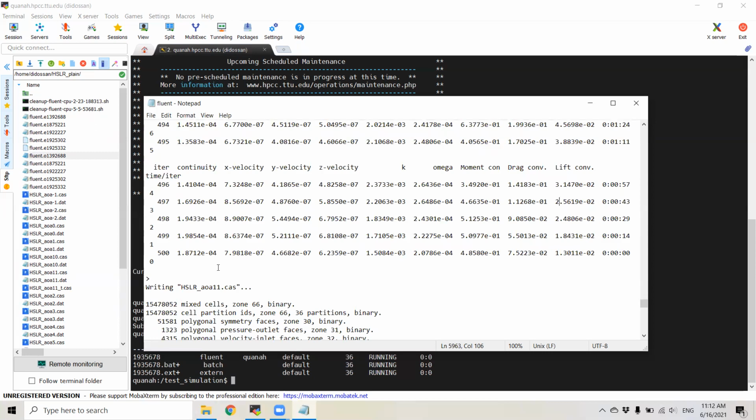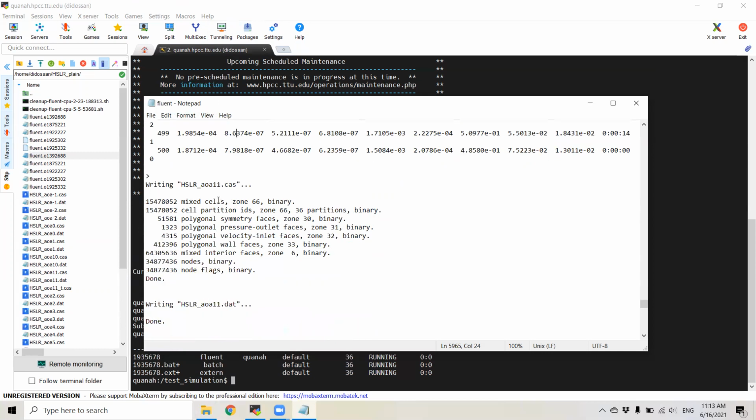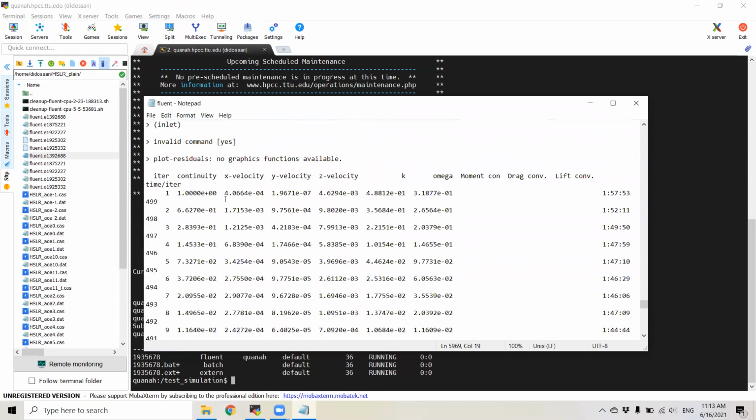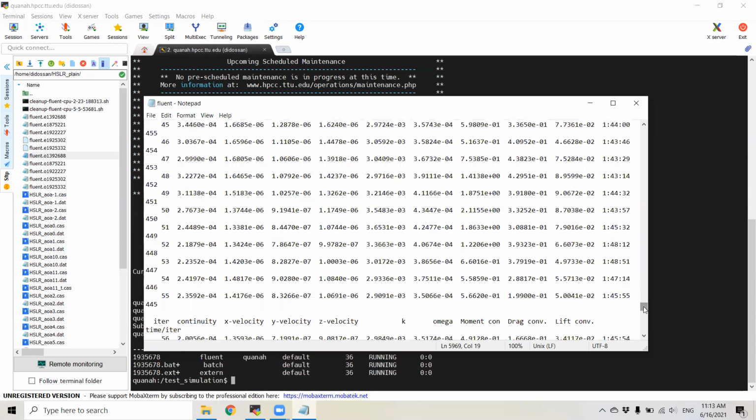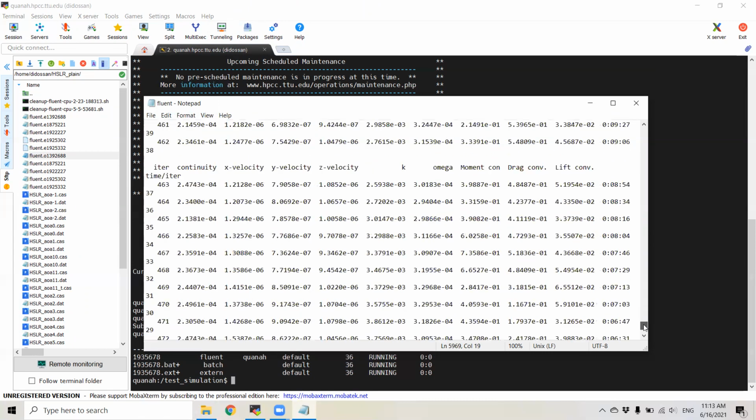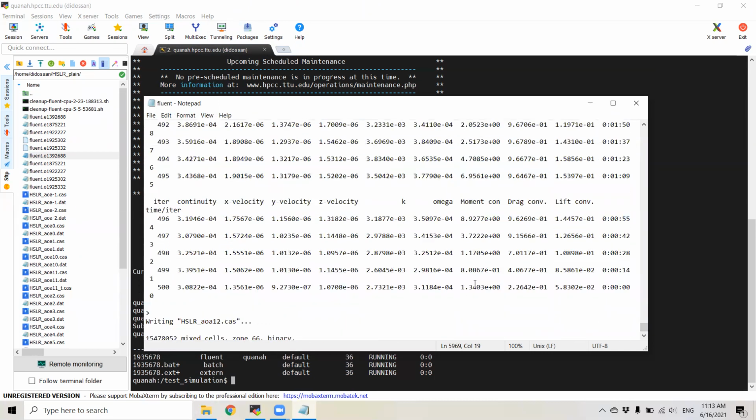And so we know that 11 degrees is the highest that we can, I mean, sorry, 10 degrees, which was the previous case, was the maximum angle of attack that we could solve by the steady simulation. So now, of course, 12 degrees will also be the same thing. We will not find convergence in 12 degrees since 11 degrees was the maximum. 12 won't even give good results.